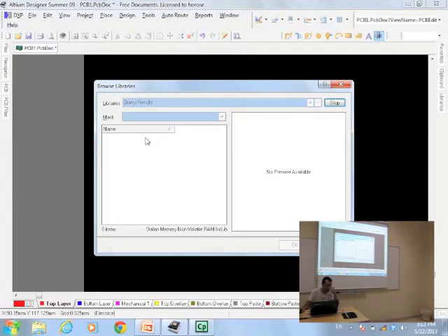Your transistor, what is your transistor? 2N3904 and 2N3906? Yeah. They are called TO92. Their package name is TO92. Okay. The package of that regulator is TO220, and there are lots of other packages. If you learn them, it's very fine. But most of the packages are provided in these kinds of software. You don't need to design them again. Just as an object, you can bring it into your app and do this.